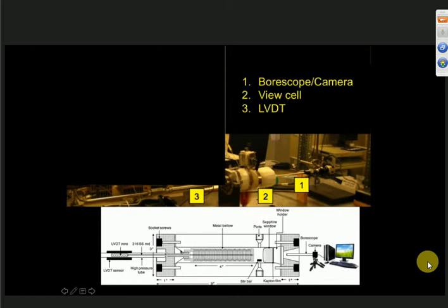The rod's back end is connected to a sensor element, the LVDT sensor element. As the bellows moves back and forth, when you go back, you're depressurizing, and the position changes. So you can track the position of the front end very precisely, up to the micron level.